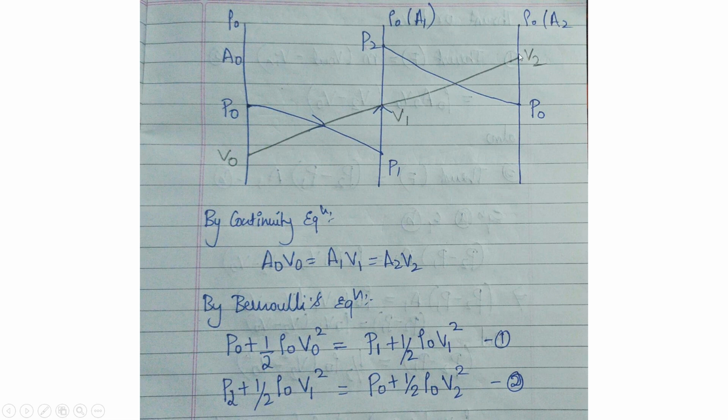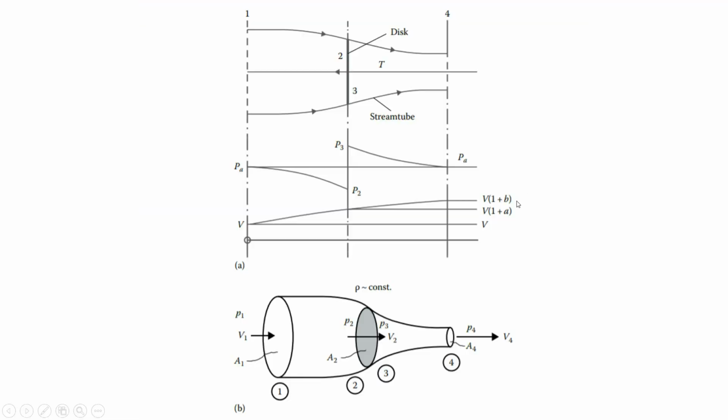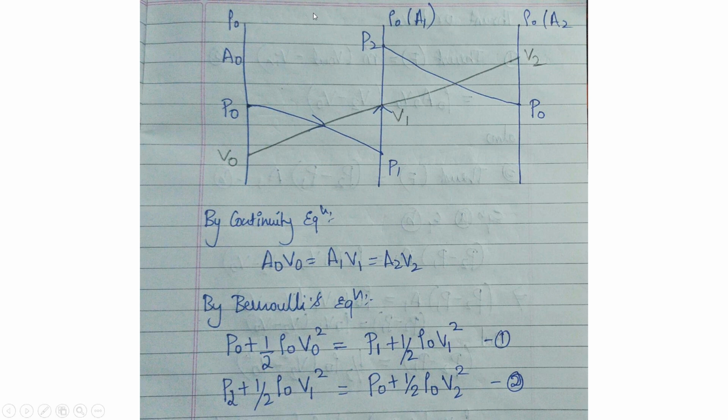If you see the velocity, it has a uniform increment, increasing uniformly as per the assumptions made, and we have completely taken out rotational flows. Some treatments consider slip and rotational flows and include extra terms, which is not necessary; it will complicate things but end up with the same values as we would obtain with this method. I hope you understood the boundary conditions.